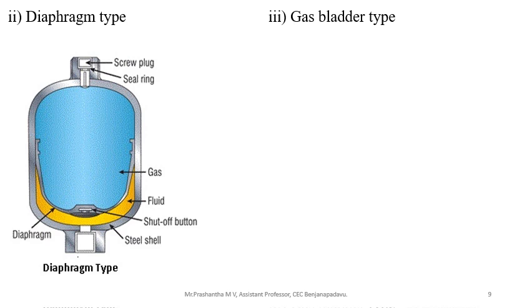When the oil is delivered into the accumulator, it deforms the diaphragm. The gas is compressed when the charged oil pushes the diaphragm against it. This gas pressure is used as the potential energy to force the oil out when it is required in the circuit. See, look at here, there are two chambers. See here, this yellow colored is the liquid one, this blue colored is the gas chamber.